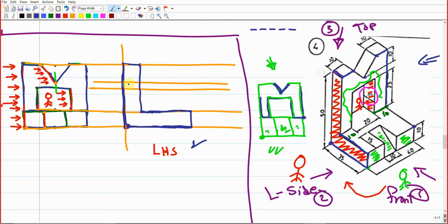So if you try to draw a dash line over solid line, there should be dash line, dash line, and dash line. This is the projection of this opening from the side view. But it should be seen as a dash line. So if you draw a dash line over a solid line, it will be seen solid. Dash line over solid line, it will be seen solid. So we're just going to end up with just one dash line in this way. Make sense? So we got one feature.